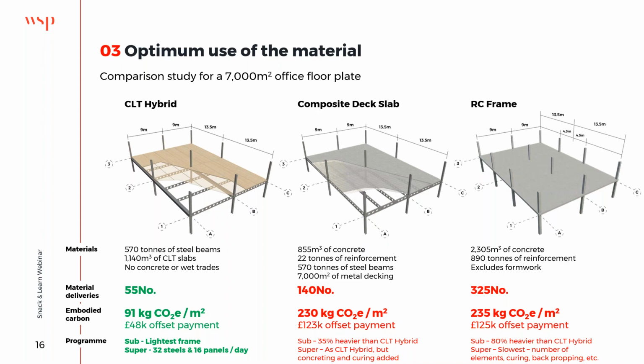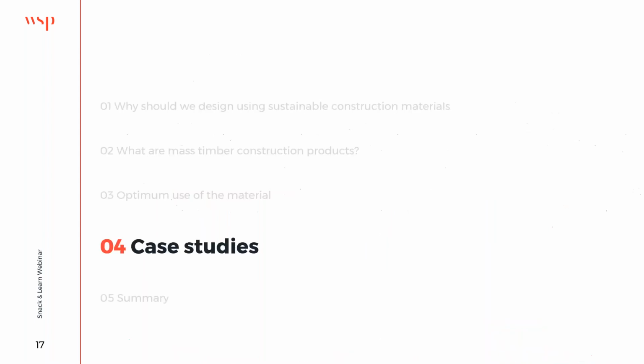And then if we look at the erection of the superstructure, it is erected in the same period of time as it takes to place the composite deck via the shear studs. However, in the composite deck solution you have got to lay the reinforcement, pour the concrete, and allow it to cure before you can traffic it. So the CLT hybrid is erected faster and therefore opened the soonest. Those are the kind of differentials that you wouldn't necessarily realize for that solution.